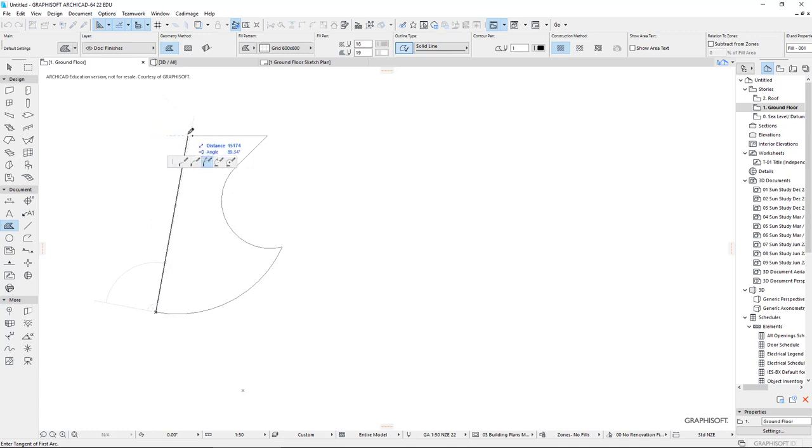We've got our alignment points here, so ArchiCAD automatically senses where we started, and it automatically senses vertically up. When we get to that vertical intersection there, you'll notice my pencil disappears and I just have a little dot at the end. If I go back to where I started, my pencil fills in black, click once, and it finishes that operation. So that is now a polygon area.